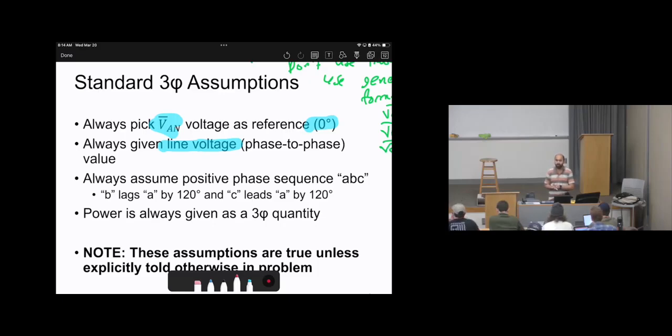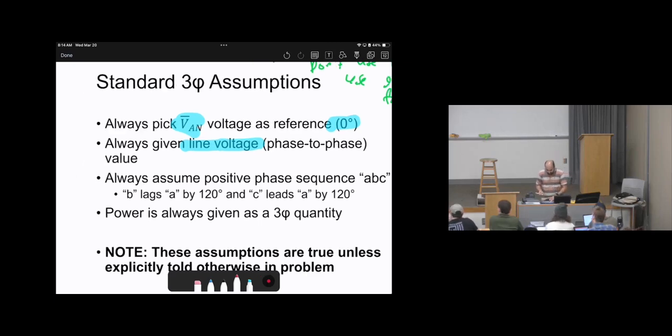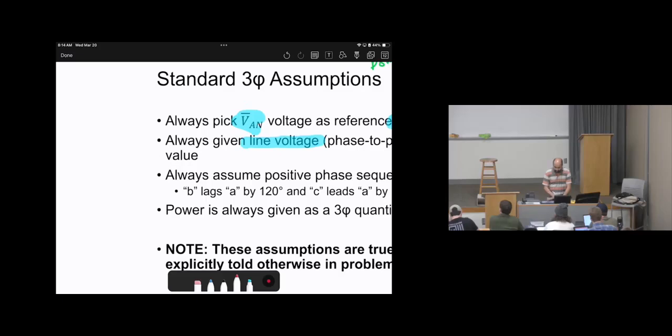The default, if there is no indication saying this is V line to line or this is V line to neutral, is that this is V line to line. So when we see any label with a voltage, it is V line to line equal to this value. For example, if a system has 500 kilovolts without mentioning anything, you will say V line to line equals 500 kilovolts.